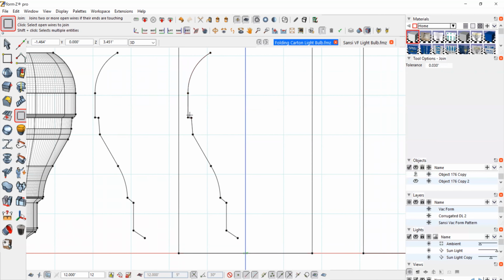And I'm going to do this little one. This one. So these points are telling me that these things are perfectly lined up. I don't want 2 little points close to one another. That's coincident points, and that causes problems in geometry. Okay, so now I'm selecting this whole profile, and it's all one line.